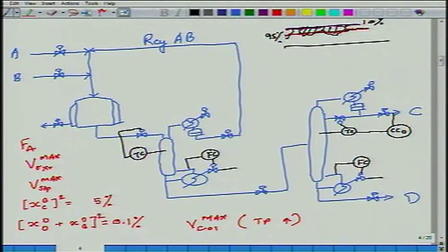If the temperature is going down, what does it mean? That means light stuff is leaking down, so put in less feed. If the temperature is increasing, that means the light stuff going down is decreasing, so increase the feed. Yeah? Will this be tight?